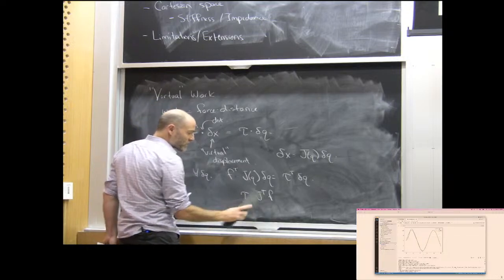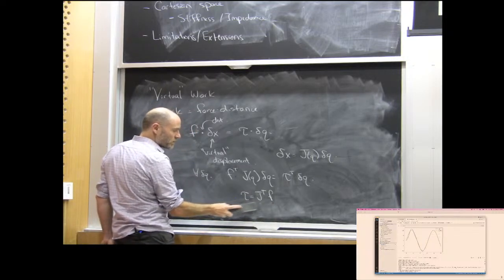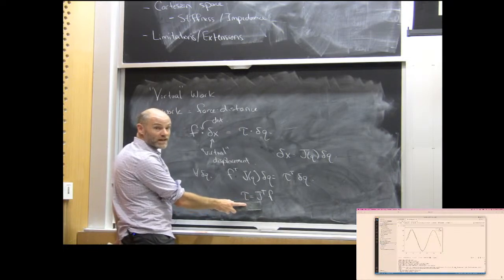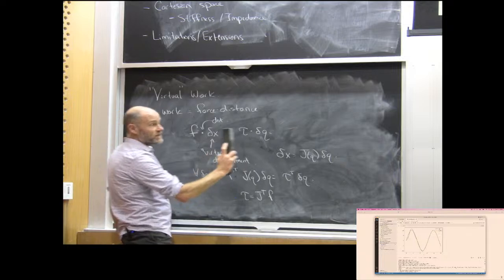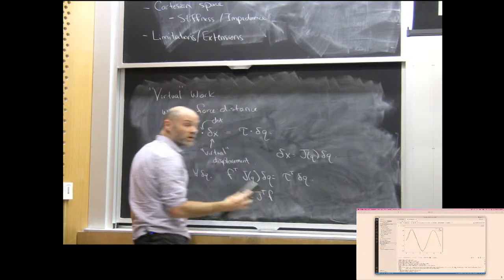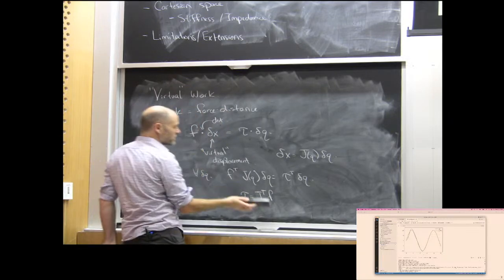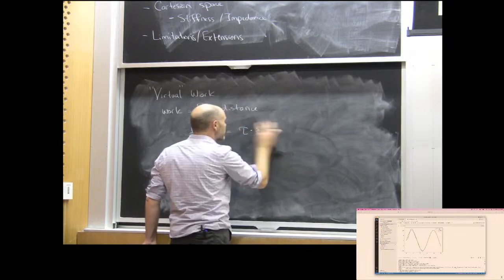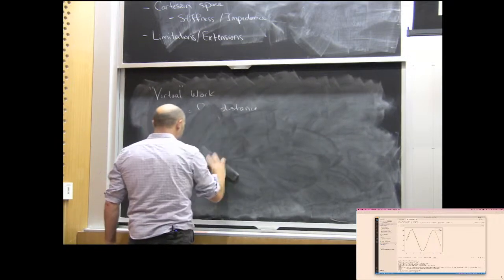It turns out this translation between the Cartesian space and the torque space with the Jacobian transpose can actually be applied to the entire multibody equations. And the result of doing that is one of the most beautiful results on our list here, which is this idea of writing Cartesian space dynamics, task space dynamics.